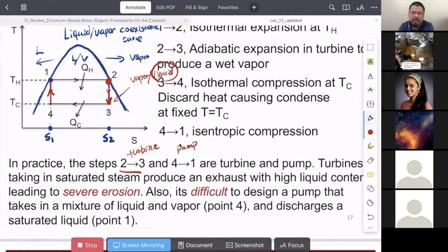So the turbine, after a few years, we have to replace the blades. That is not too encouraging for the real application. So this is challenge 1, simply because the liquid water at relatively high temperature would be quite reactive with all those metal materials, metal and metal oxides, even with the steel itself.